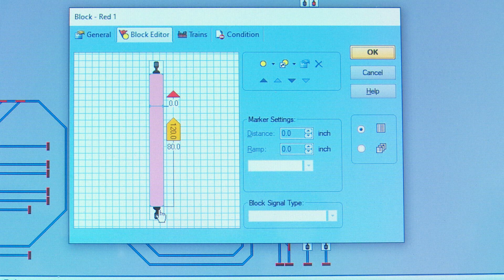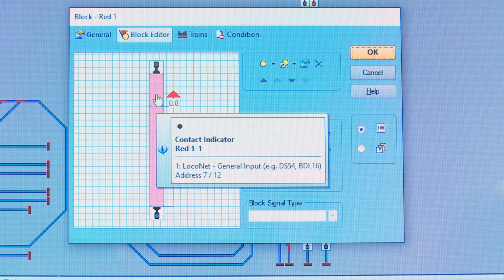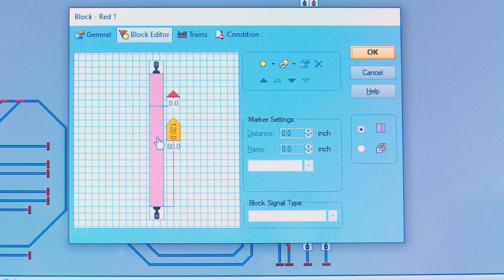Well, what I've decided is the train will come in for about 80 inches and then slow down to a crawl speed after 120 inches, and then when it hits this stop mark here, the brake mark between the two blocks, it should stop as soon as it detects current on the front bogie on the next sensor input. So that's the main length, and this is the short length.